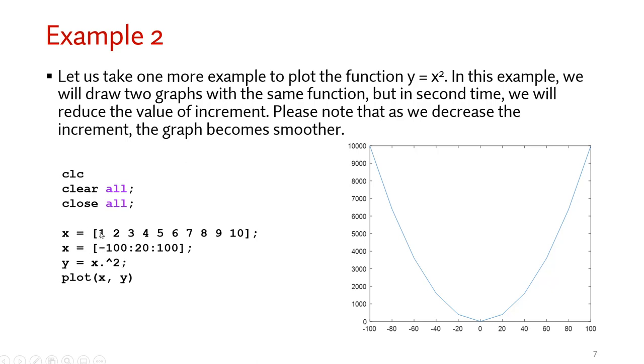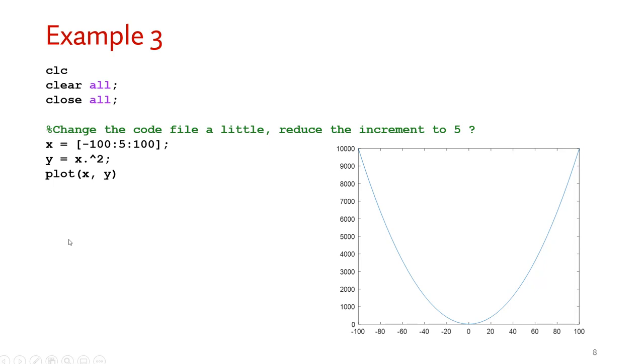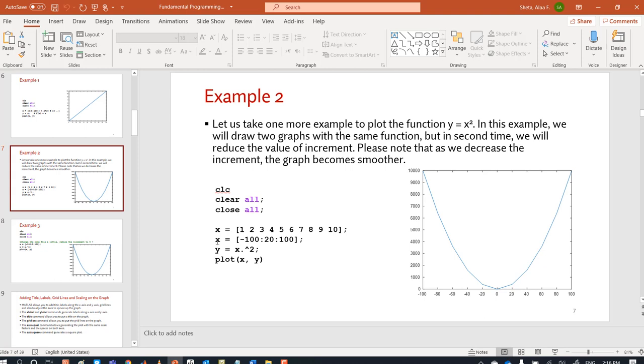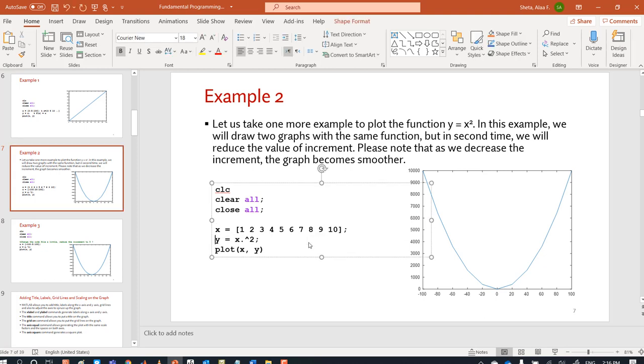Now look at this. This way, actually, what you have is two arrays with x. So the first array will not really work, because when we say x equal from minus 100 to 1, you are overwriting x in this case. So just make sure of this; it is a mistake we sometimes make in MATLAB, which is drawing a function or defining a variable, and then we draw over that variable.